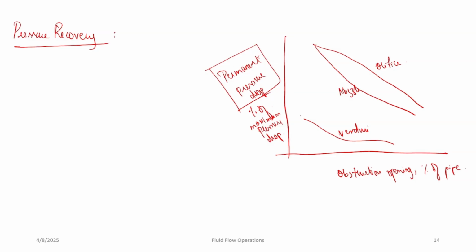After the difference has been generated in the differential pressure flow meters, the fluid passes through the pressure recovery exit section, that is the diverging section, where the differential pressure generated at the constricted area is partially recovered. The pressure drop in orifice plates is significantly higher than in venturi tubes.